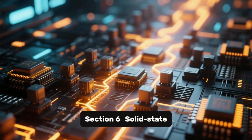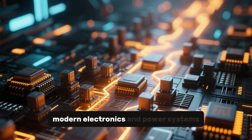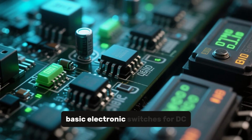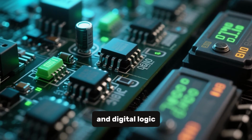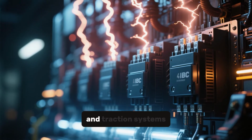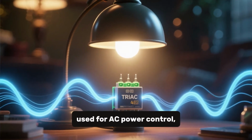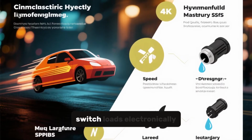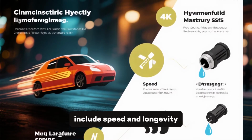Section 6. Solid-state switches and semiconductor switching. Semiconductor switching dominates modern electronics and power systems. Diodes, MOSFETs, BJTs: basic electronic switches for DC/DC converters, load switching, and digital logic. IGBTs, used for high voltage, high current switching in inverters and traction systems. Triacs and thyristors, SCRs, used for AC power control, dimmers, and controlled rectifiers. Solid-state relays: SSRs switch loads electronically with no moving parts. Advantages include speed and longevity.